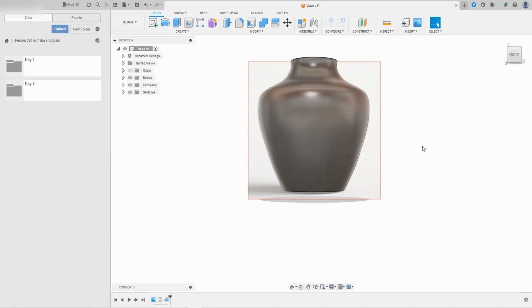However, this is accomplished by taking the 2D profile and extruding it along a specified path. This is particularly useful when creating linearly directed curves, objects such as pipes, wires, and handles, which we can also add a twist angle to, which will turn the 2D sketch as it is swept along the 3D trajectory. But for now, let's keep it very, very simple. Let's see how we can use the sweep function to fix our vase.